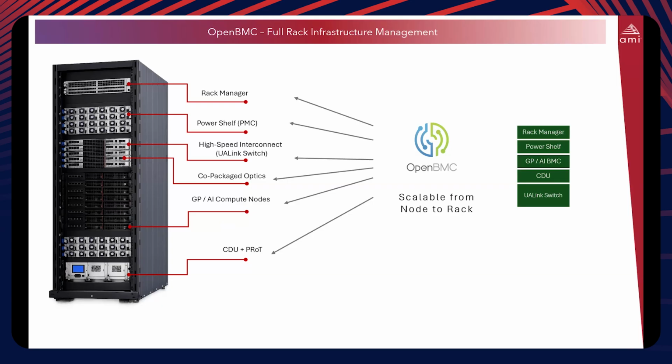Redfish, which has replaced legacy IPMI, has become a de facto standard for out-of-band management. OpenBMC embraces Redfish, and it has support for various hardware interfaces. It is highly modular and scalable. So these qualities make OpenBMC deployed in all of these devices for out-of-band manageability.